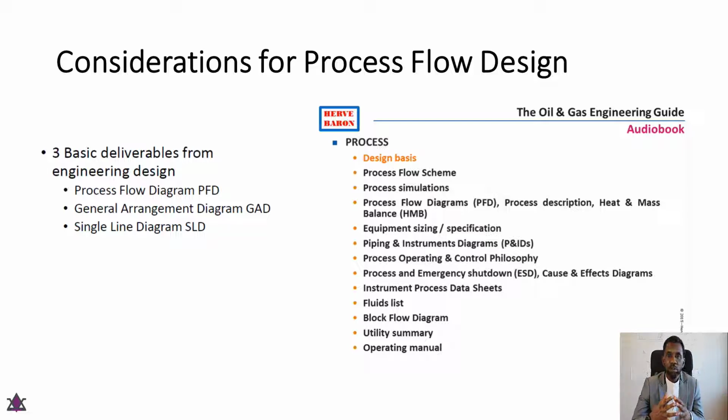In terms of carrying out the GAD drawing, it's not really realistic to carry it out without the process flow diagram, because it's from the process flow that you will know which equipment comes after which equipment, which process unit comes after which process unit.